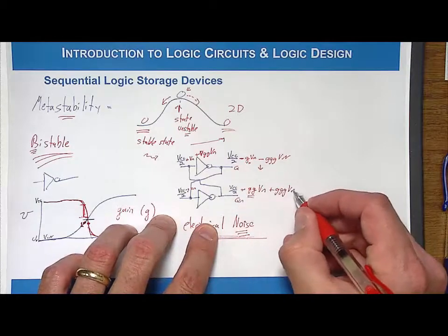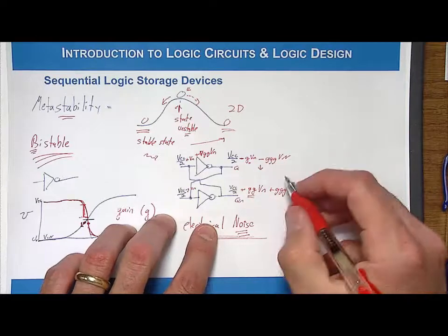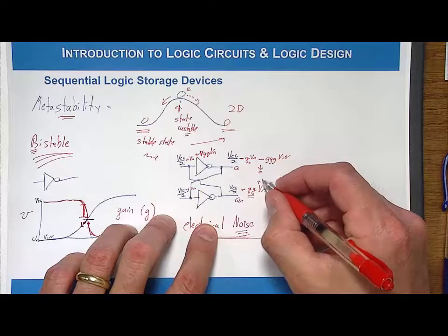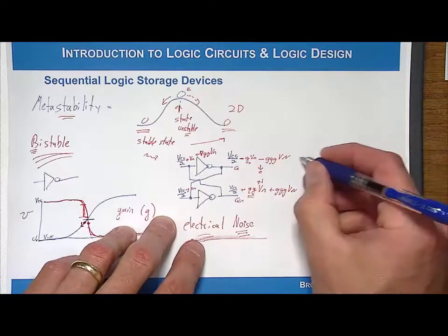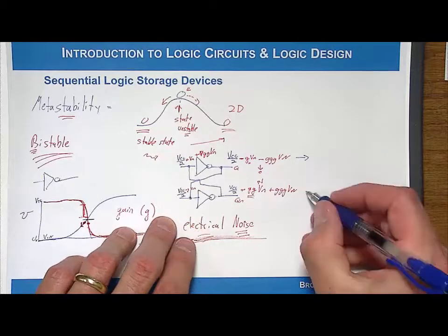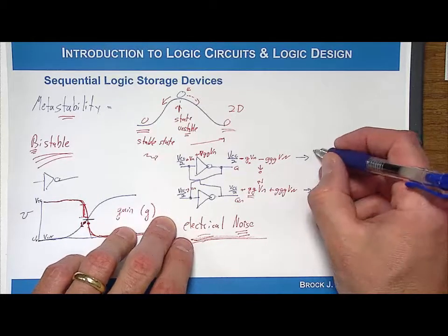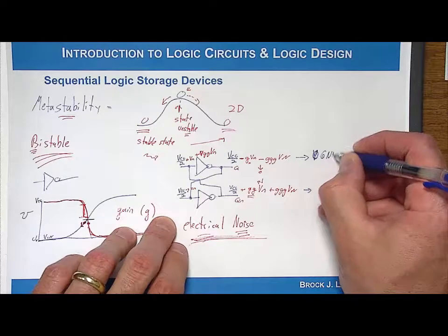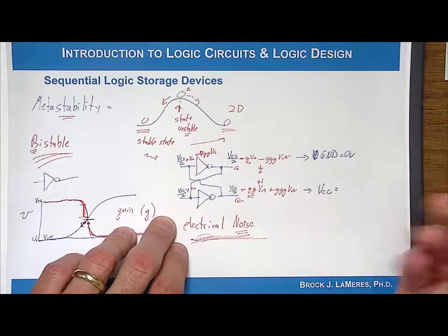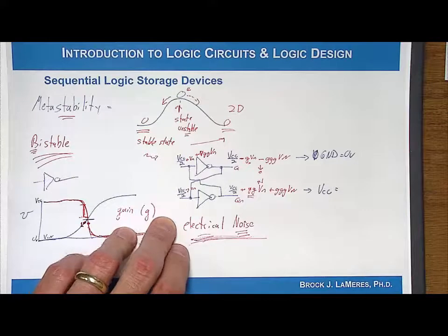And so where does it end? Well, it turns out that it ends when this goes to a logic 0 and this goes to a logic 1, or said another way, these will ultimately go to the maximum and minimum voltages in the system, which we know is ground, or 0 volts, and VCC, which is whatever power supply voltage you're using.